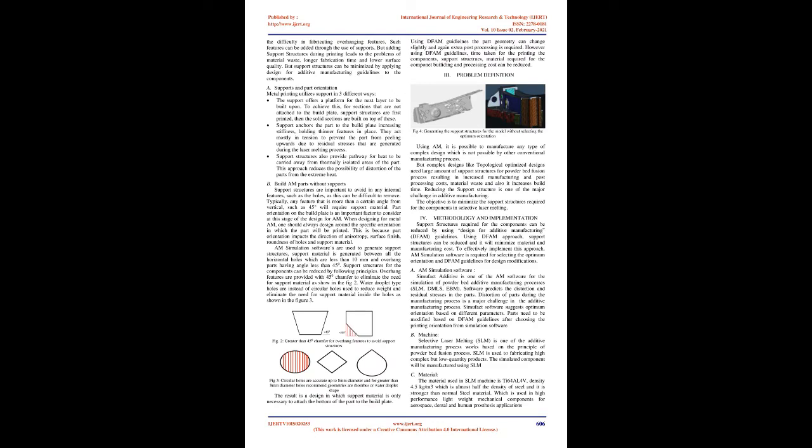The most common reason for parts not being successfully manufactured is printability issues like residual stresses and distortions in the AM process. However, simulation software and design guidelines are used to minimize the residual stresses and distortions in the components. While the level of part complexity that metal printing is able to produce exceeds that of traditional manufacturing techniques, there are certain design rules that must be followed. Metal printed parts are anisotropic and can be produced from common engineering metals, such as stainless steel and titanium. However, the conditions under which metal printing is cost-effective depend strongly on the geometry of a design.